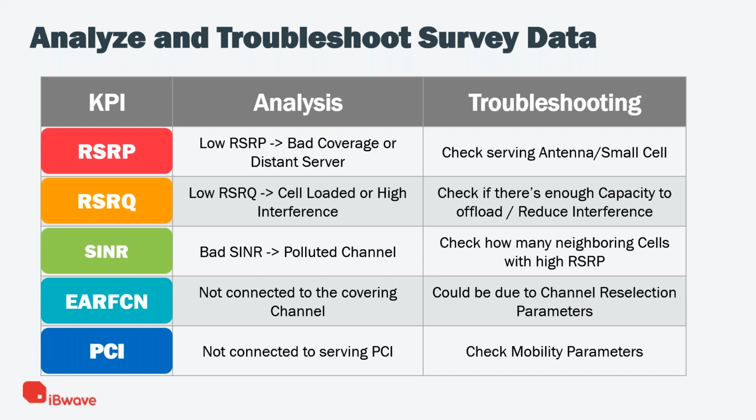Why? Because when you reduce the power, you're taking advantage of the environment. If I am receiving 10 interferers at maximum power, and I reduce the power, let's say by 3 dB, maybe 1 or 2 interferers will not be visible anymore. They will be below noise. And then their composite power is not taken into consideration anymore when I do my SINR, and I'm not considering them as interference. They're just noise. So they drown in the noise. So that's one thing.